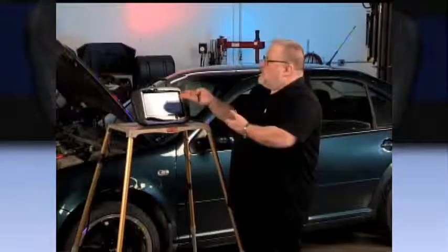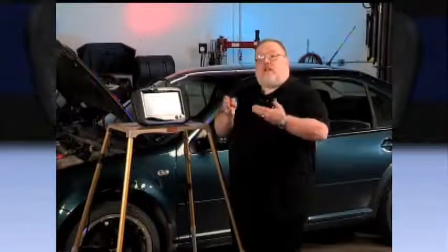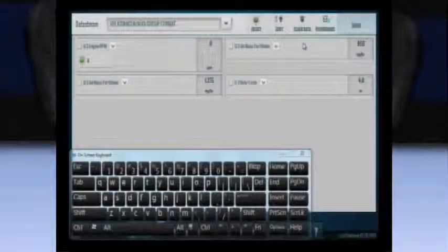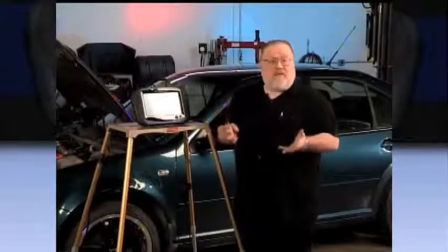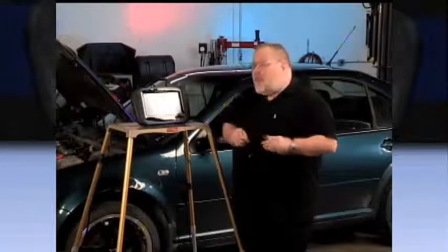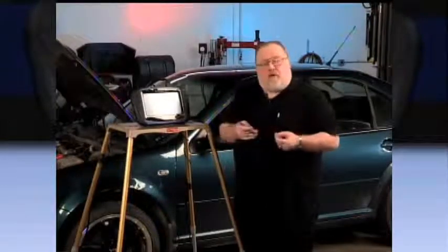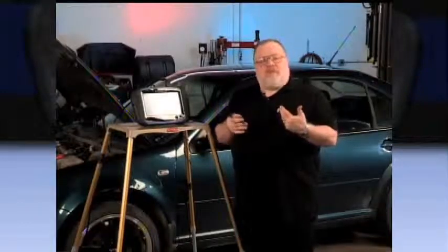Now, if I had a situation where that mass airflow reading was significantly lower than those numbers that I was talking about, now I'd want to start doing some physical inspections to determine, do I have carbon buildup, do I have a physical problem actually within the intake manifold itself. All right? Another potential problem for low power would be a problem with the vehicle turbo.